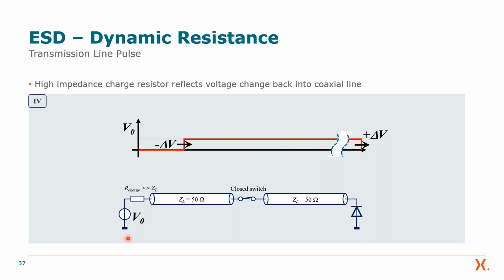The window is very, very large, and you cannot really understand what is physically happening if you have these complex pulses exposed to your system. So the idea was to have a very, very defined environment of a 50 ohm transmission line, and to have a high energy pulse which is traveling down this 50 ohm line.